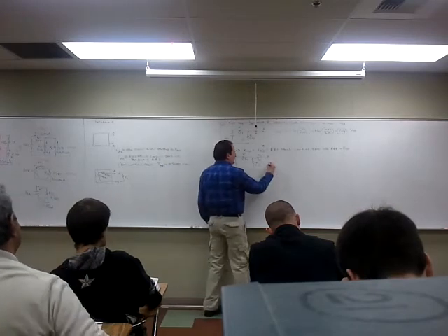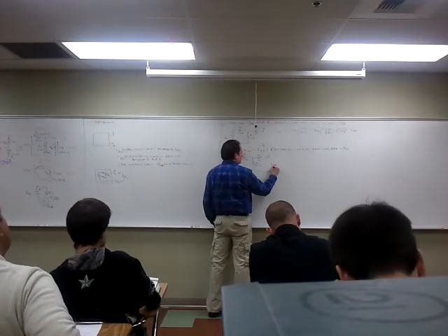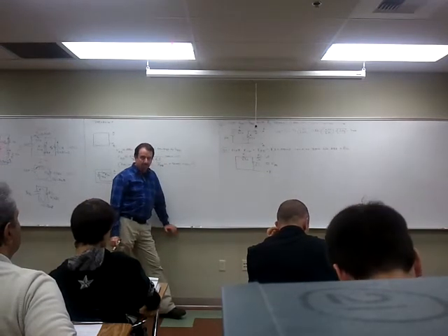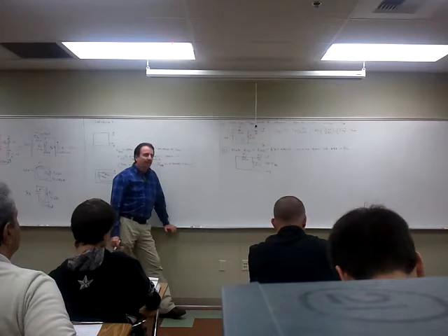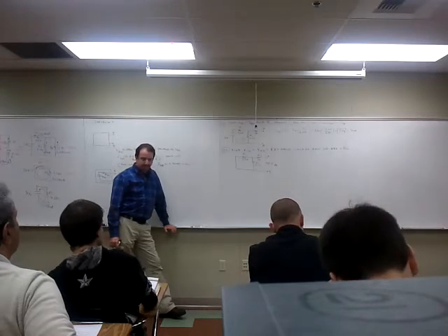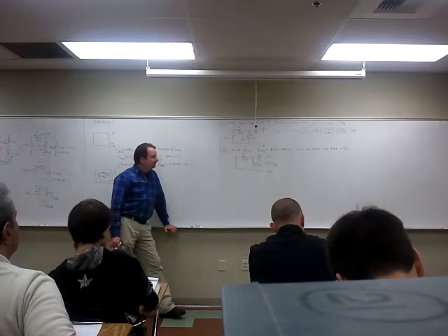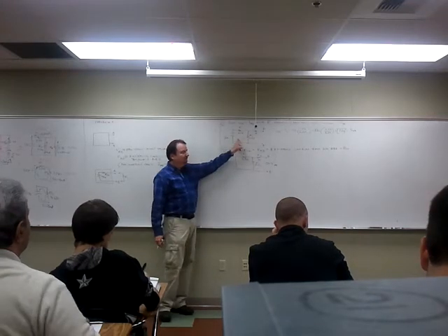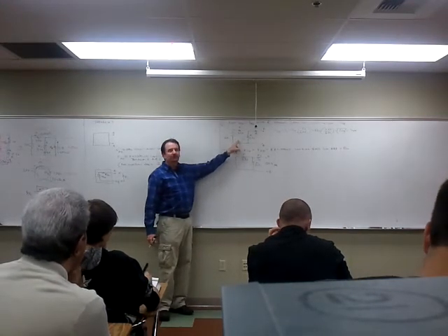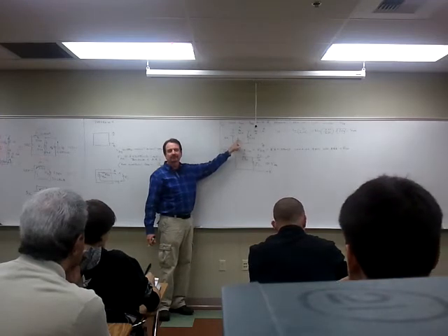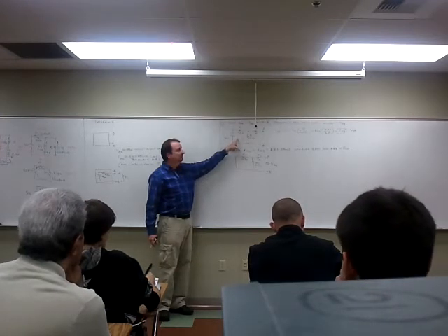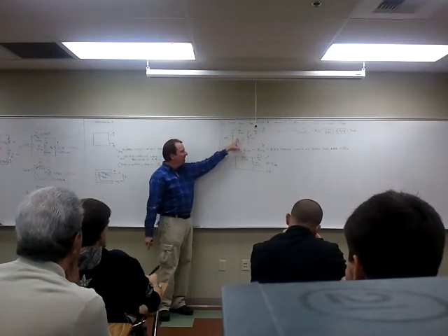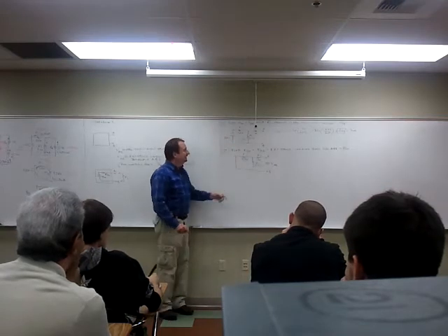And the resistance, R Thevenin, is the resistance from A to B, looking back in. It's like finding R total, but from the opposite side of the circuit. So let me ask this. What is R total from the point of view of the supply? The normal way you found R total, what is R total in this circuit? 5.5K. It's just adding these two resistors.